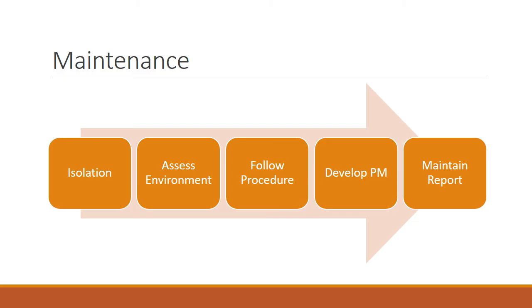Now, many of your preventive maintenance choices may be guided by knowing what sort of environment your switchgear is in, which is essentially our second step. Is the dust on the switchgear from regular outside dust, smoke, or coal dust? Cleaning products and supplies such as vacuum filters and rags may be required for varied types and amounts of pollutants that your switchgear may be accustomed to in your environment.